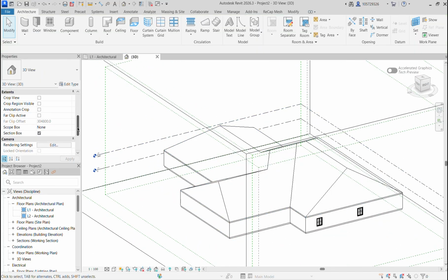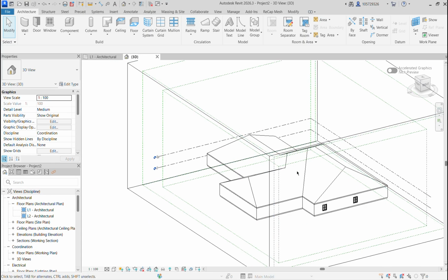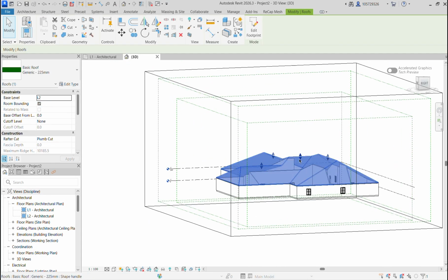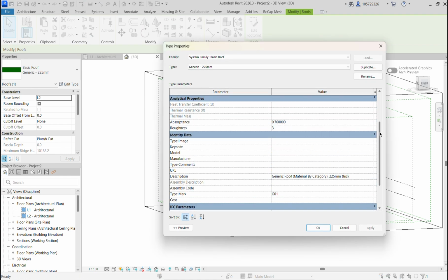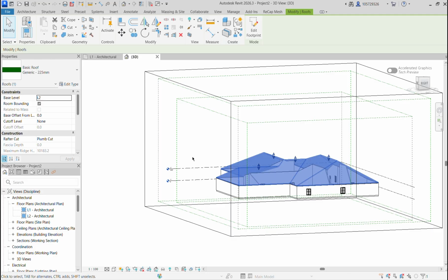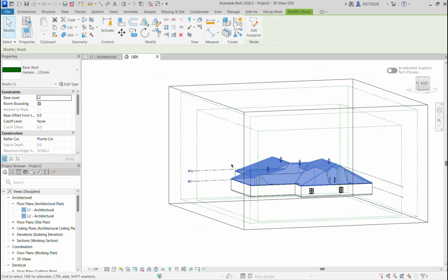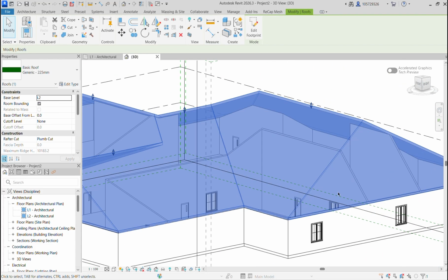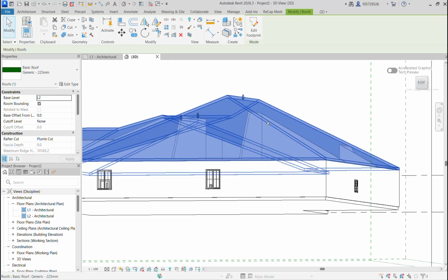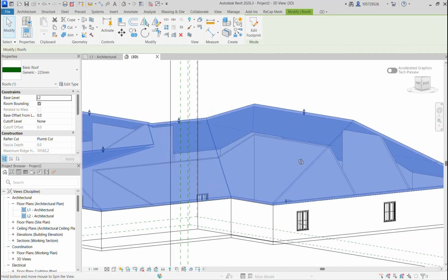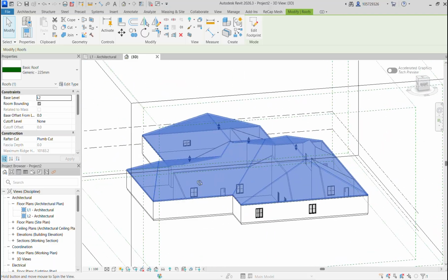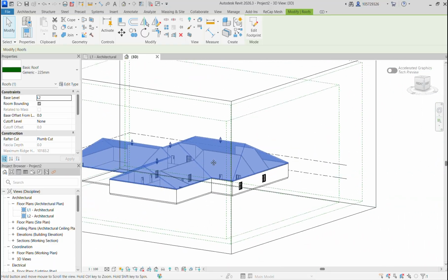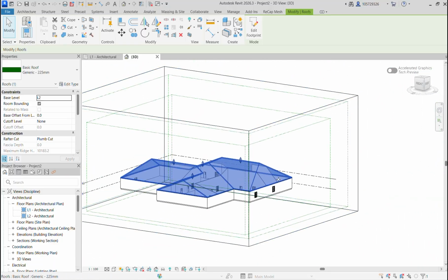If there's a specific height or length you'd want your roof pitches to be, it could easily change up under edit type as well, and all the properties should be under here. If you click on the roof, you could clearly see that those walls are attached to the topmost of the roof. So that's basically the attach setting of those walls that Revit asked earlier.